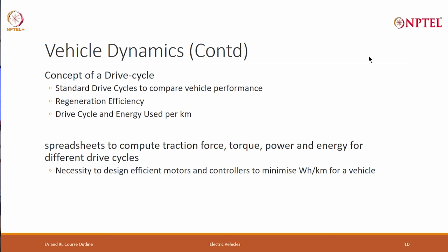To that extent, my braking does not lose the energy. Of course, it will lose some part of the energy. Part of the energy is recovered back, and that is called regeneration efficiency. I do it on a slope. I also do it when, suppose I am running at 70 kilometers and now I have to slow down. I will apply the brake. Can I make it regenerative? That much energy I will not lose. In petrol vehicles, you just lose that energy. Now that's an important component, because I can recover that energy, charge the battery, and to that extent my efficiency goes up.